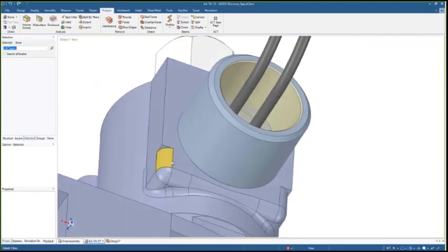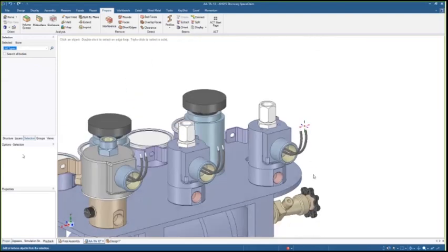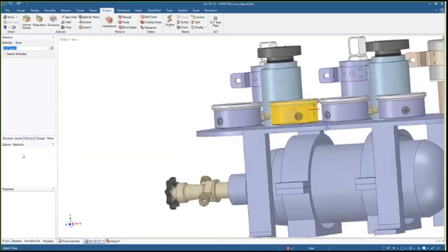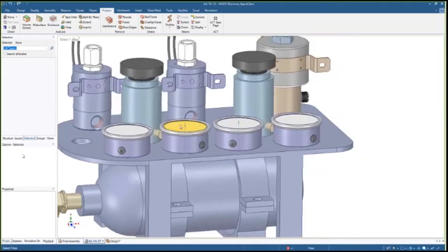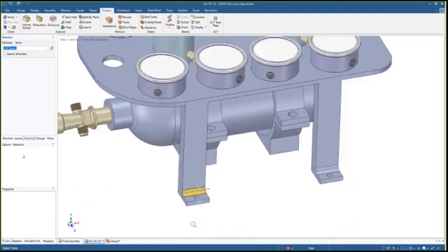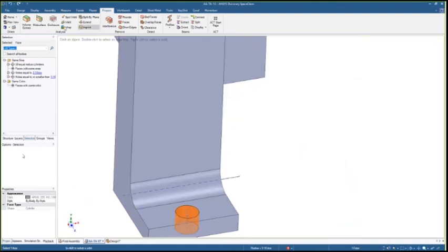But I do realize with the clock here that we are coming up on the time, so I want to move past the round removal. You kind of saw how that process can go, because another thing which can complicate meshing are holes. Maybe I don't want holes in the model. So if I select one and fill it in, F for fill, it removes it.